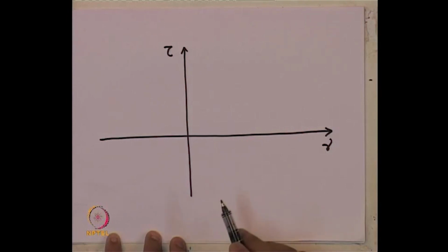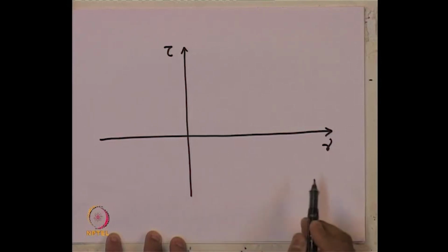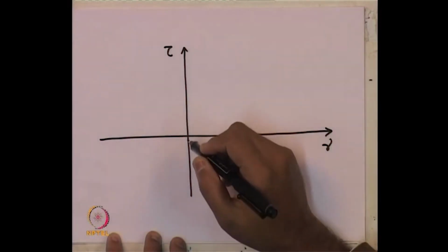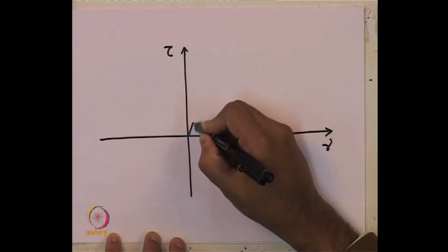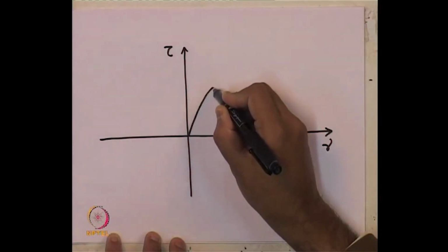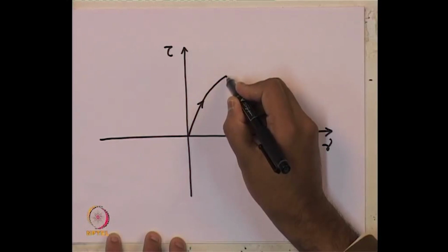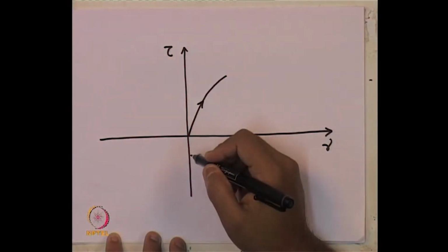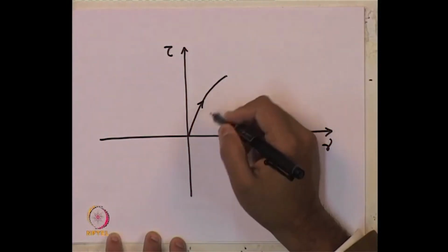So, what is the behavior of shear stress development for different cyclic shear strain? We want to measure it through the laboratory test of cyclic triaxial test or cyclic simple shear test. So, how can the variation for any particular sample go? Suppose the path followed is like this when we keep on applying the cyclic load on the sample. So, cyclic strain is also increasing and shear stress is also increasing. Now, after reaching a certain point, let us say we withdraw the load.